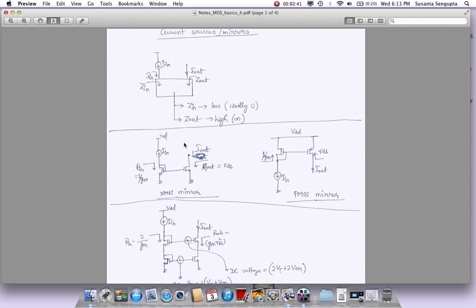How or what kind of circuitry looks like current mirrors? A simple one is this, which you might have seen. You have a current source which is actually generated from some other circuitry in the chip. It's giving you the current. You put it into a diode connected NMOS device, and let's say if this was 1 to 1, then it takes the current in and it mirrors the current out here. So I out becomes equal to I in, or if this is in some ratio, some 1 to n, then this will be n times I in.